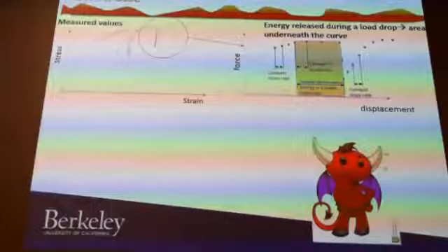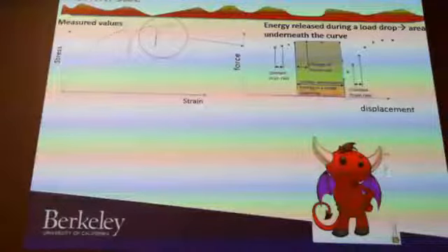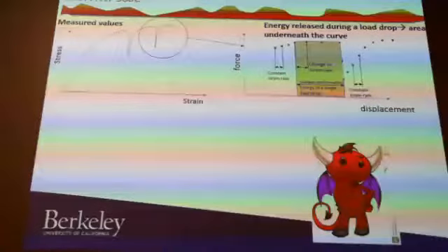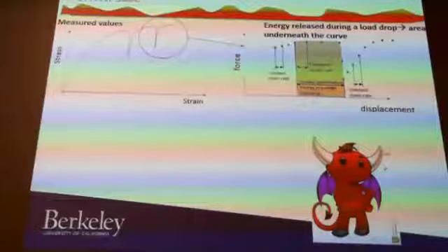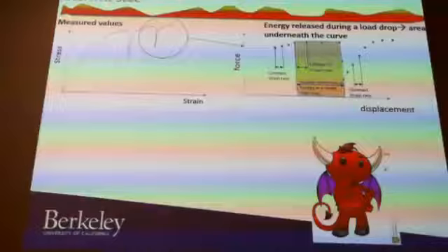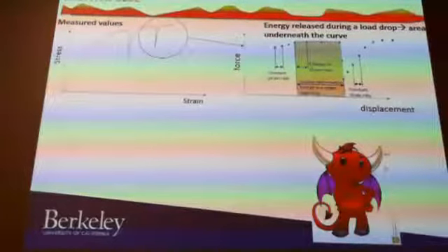And that's bad. So if you understand the slip step systems and the way they move, the way they pile up at the grain boundaries and how much energy it actually takes to break them loose, you have an understanding of one of the worst failure mechanisms you can envision in nuclear material, which is sudden localized fracture.